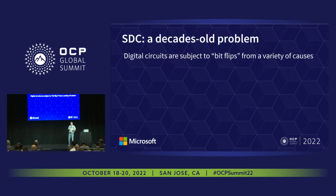And some of the reasons why that can happen are defects. So this is a manufacturing error that escapes manufacturing time testing into the wild, or it can be a latent defect that actually manifests in production life. It can be a marginality, which is a process variation conspiring with environmental conditions to take a circuit outside of its operating margins and thereby cause a corruption. It could be wear-out effects like electromigration or oxide wear-out that actually cause the circuit to degrade over time and then fail before its designed end of life.